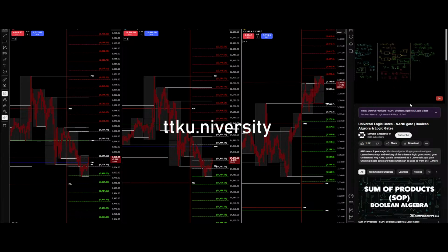Now we supply this A and B the whole complement as input to the second NAND gate. We have A and B the whole complement over here, as well as A and B the whole complement over here. So the output of the second NAND gate would be the complement of A and B the whole complement AND-ed with A and B the whole complement, of both the inputs.